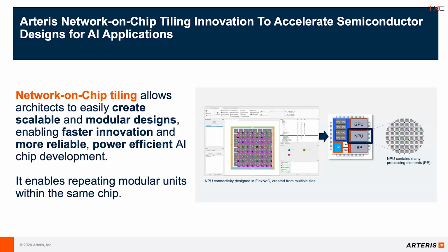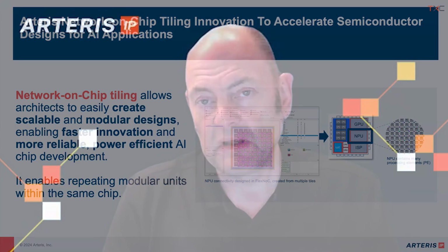easily just by defining one unit and multiplying out, and taking advantage of the voltage and power saving facilities in the network. That bolts into each tile, and each tile can then be manipulated in terms of, for example, frequency scaling in blocks or domains within the design. And also, once a design has been set, a derivative design might be constructed from that. All of those tiles that are pre-configured in the previous design can be lifted, integrated wholesale, and reused very easily. So, how might this look in the tool itself?